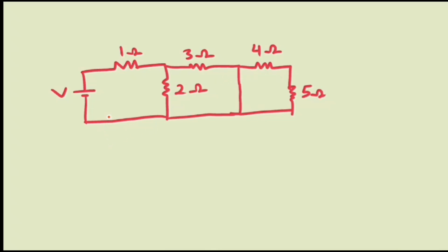So in this video, we are going to find the equivalent resistance of this circuit we have here. I have a voltage source here, then I have a resistor here, another resistor here, a resistor here, then likewise here. Whenever you are given a circuit like this, what you are going to do is trace the path of the current from the source, and always the current starts from the positive side, then it moves through the resistor here, then it returns back through the negative side.